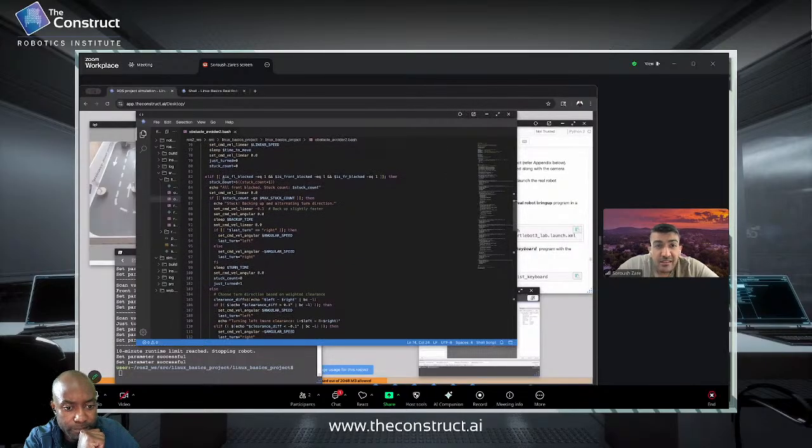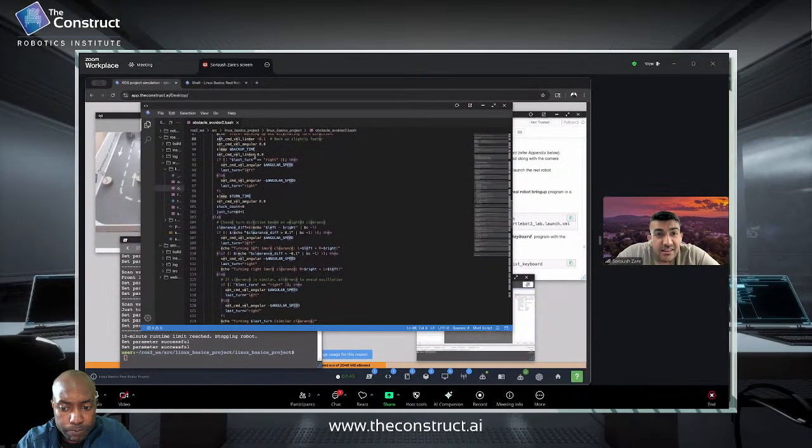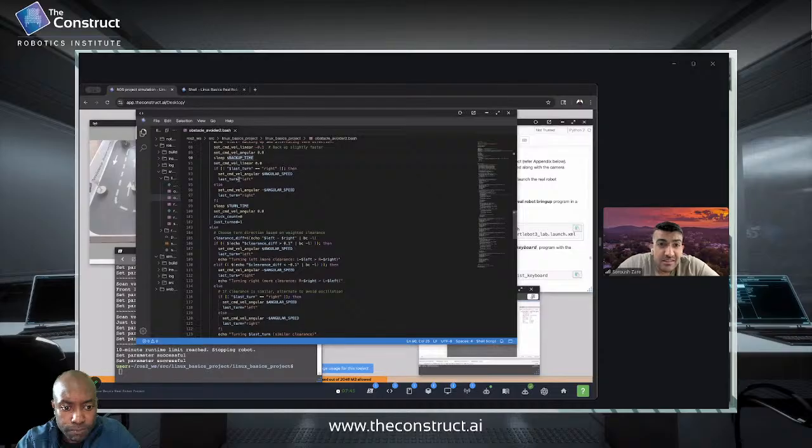And then if the front left is blocked, and the front is blocked, and if all of them are blocked, I calculate the stuck count, and if it's greater than the maximum stuck count, it stops, and then sets the current velocity to minus to go a little back. And I think this is the best way to avoid getting stuck at the corner.